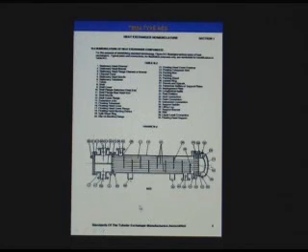Here's an example of an AES exchanger. This will be the channel. The tube sheet is the separating partition between the shell side and the tube side. It is a code design component. So in this case, if we're flowing into the channel, we would flow through the tubes into this.